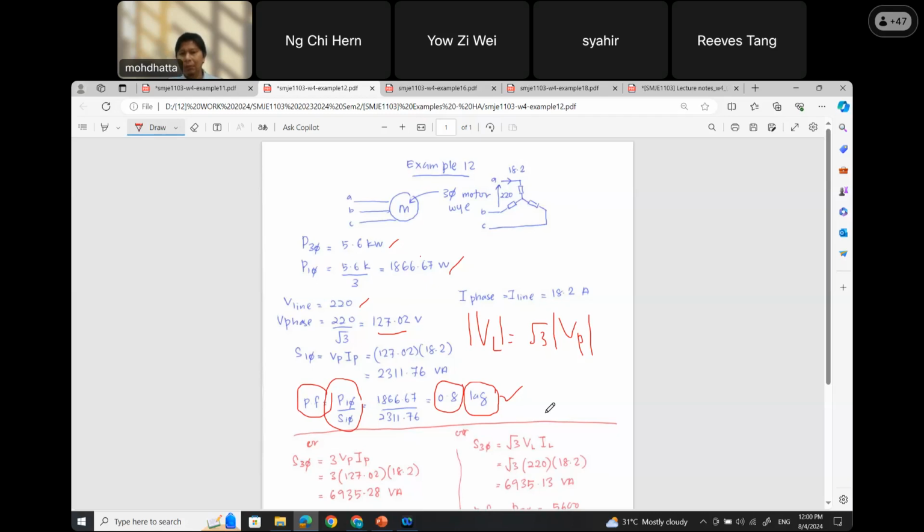But in most industrial applications, the motors applied in industry mostly come from the topology known as induction motor, which can always be modeled as an RL load. So at the end, it is a lagging power factor.